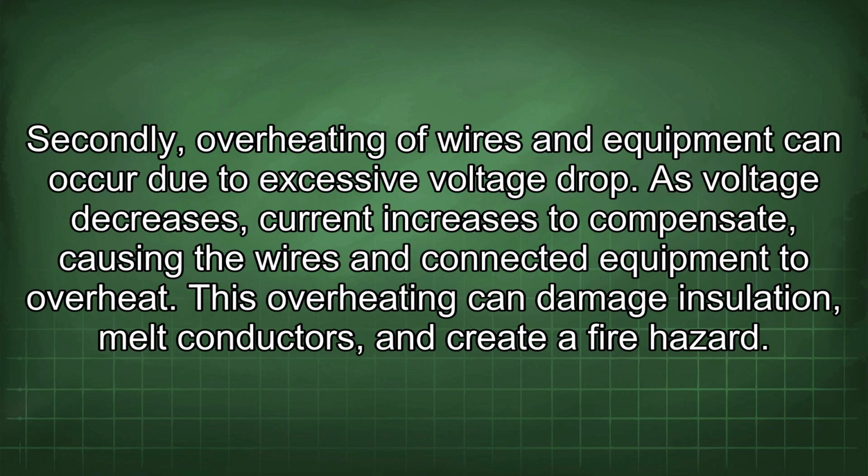Secondly, overheating of wires and equipment can occur due to excessive voltage drop. As voltage decreases, current increases to compensate, causing the wires and connected equipment to overheat. This overheating can damage insulation, melt conductors, and create a fire hazard.